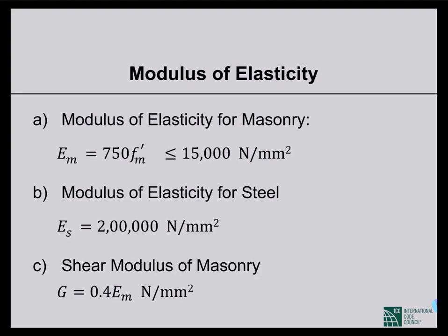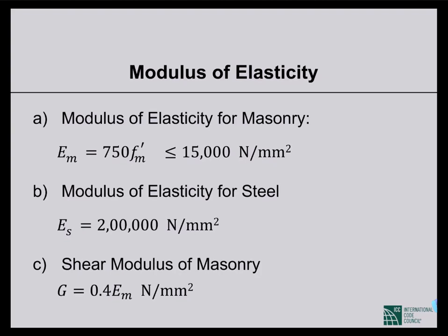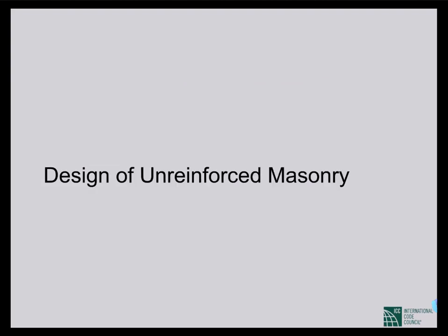So we have all the basic information, like basic geometric parameters: effective height, effective length, effective thickness. Based on these geometric parameters, we can define the slenderness ratio.